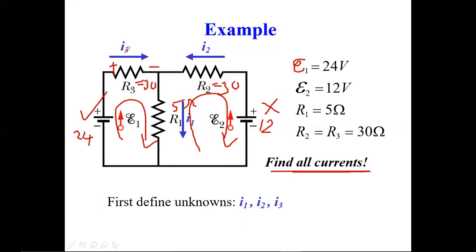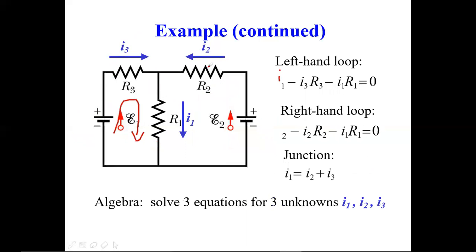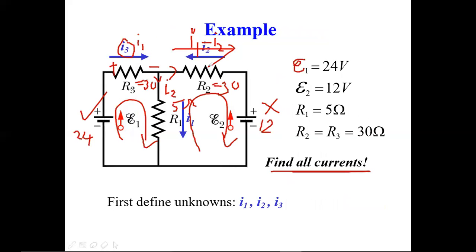If I take the current, instead of I3, I'm going to take I1. This is I1 of current. I1 is going to be split like this, 1 and 2. If this is I2, and my current direction is this, then the next one is I1 minus I2, right? So these are your assumed branch currents based on our rules, not for this slide. I took this slide from some other site, so that is the reason he has given one of the methods. I want you to go through these methods. This method gives the same answer as our rule-based method.